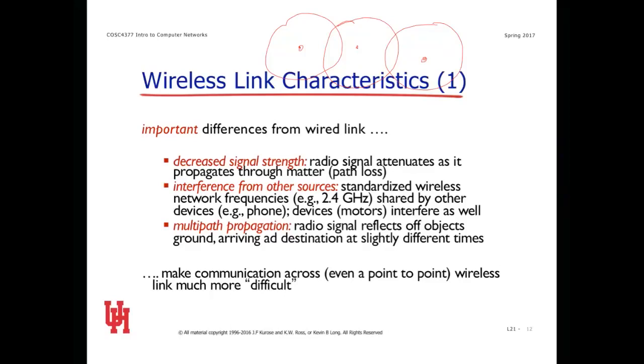So what you want to make sure of when you license these things is that you're given a license where your signal-to-noise ratio compared to the other person's signal-to-noise ratio at the boundaries of your legal transmission radius is high enough, the ratio of yours to theirs is high enough, that a typical, inexpensive, imperfect, mass-made radio will pick your signal out from theirs. That's the only thing they're interested in guaranteeing.